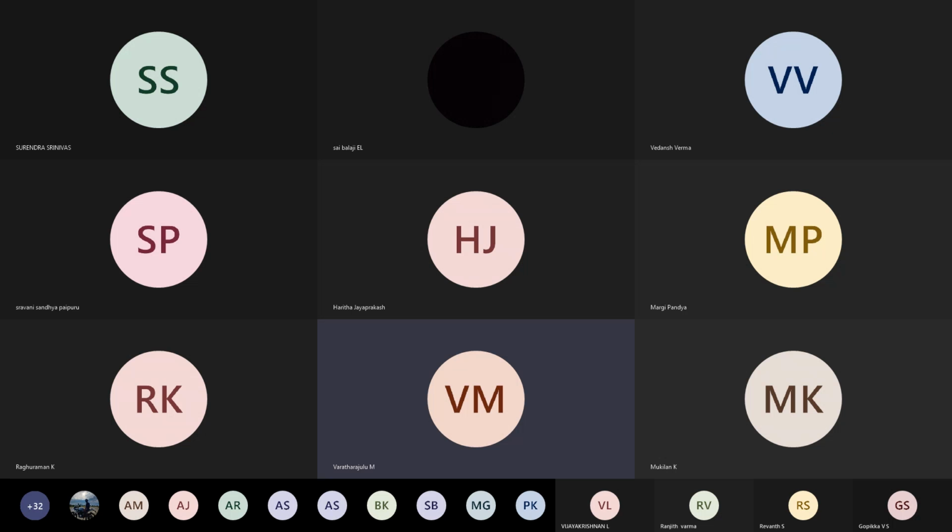Yes, Kalyan Kumar, go ahead. The first pattern is called the solid pattern. It's the replica of the product, which is accommodated in either the cope or the drag. The next is the split pattern. It's very similar to the solid pattern, but the only difference is that it's split into two halves. So the same process will be done twice.